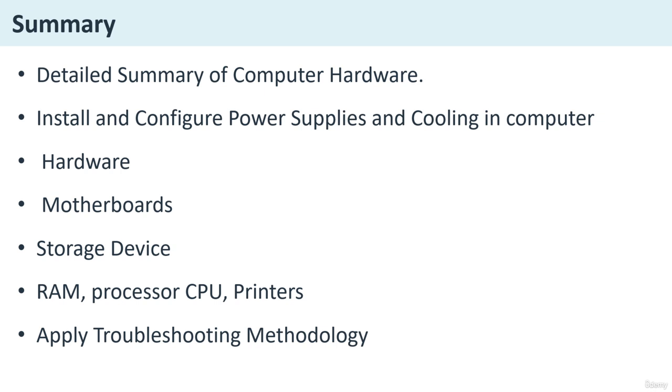Now, I will explain briefly about the troubleshooting of the cooling and power supply. Sometimes the computer won't turn on. That means check the PSU connections and power switch. Overheating can be another reason, so ensure fans are spinning and airflow is not blocked. And one more thing, loud noise may come. That means clean dust from fans or replace the faulty fans if required.